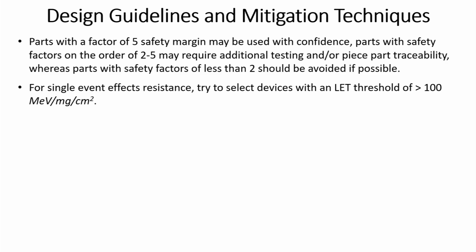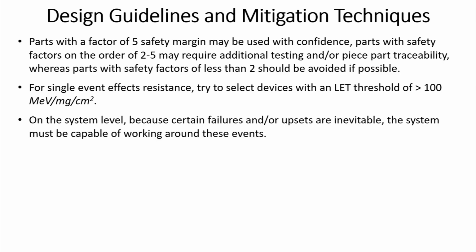For resistance to single event effects, one should use devices having an LET threshold greater than 100 MeV per milligram per centimeter squared. On the system level, because certain failures or upsets are inevitable, the system must be capable of working around these events.